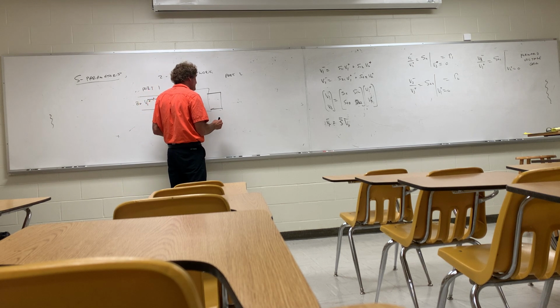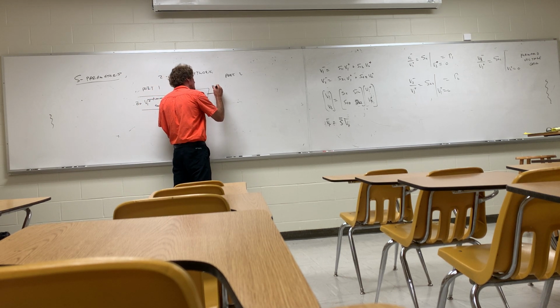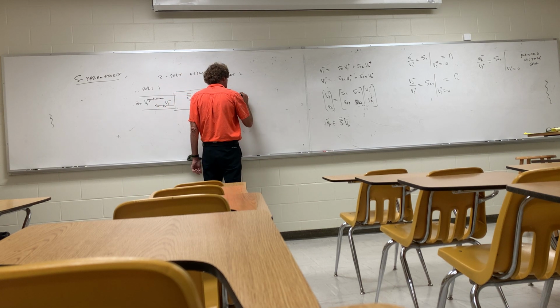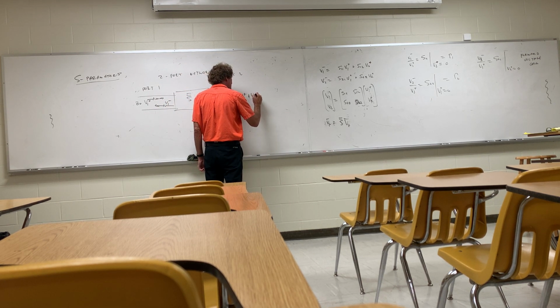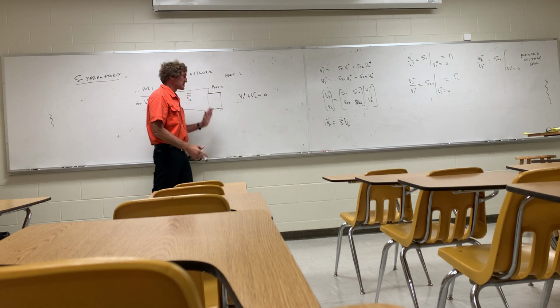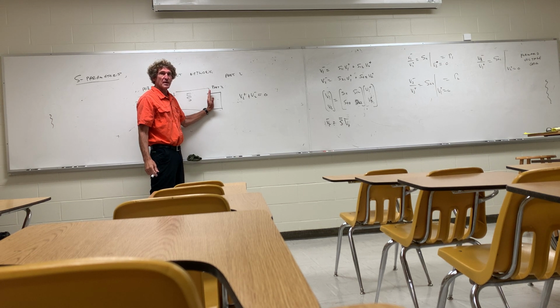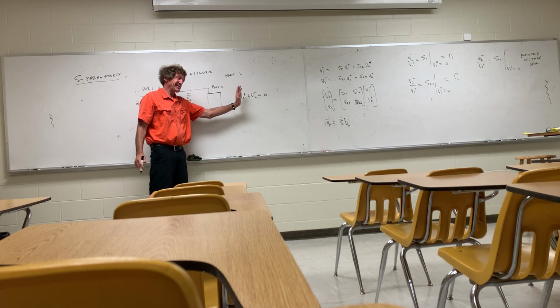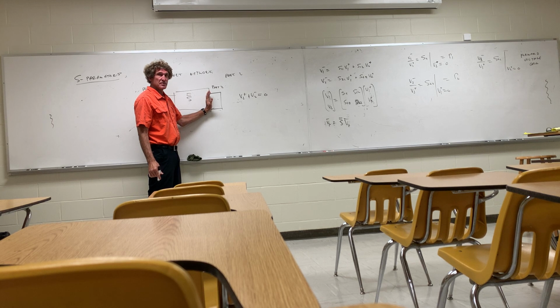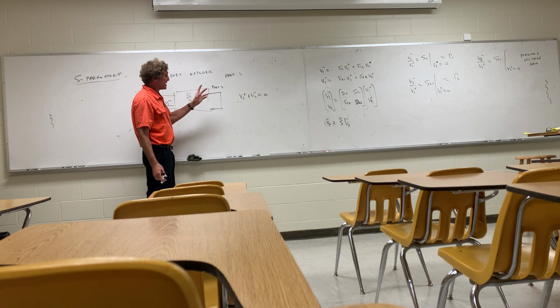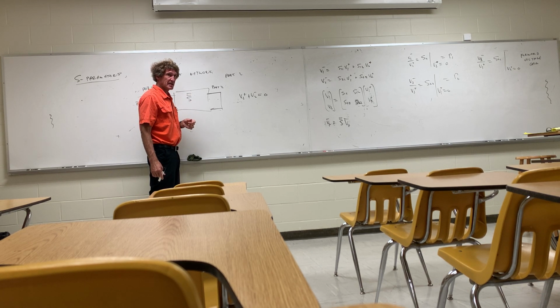This is port 2. By shorting this terminal right here at port 2, what I effectively do is say that V2 plus and V2 minus sum to 0. Y'all follow me? Because when you have a port, anytime you have a transmission line or a waveguide, you have outgoing and incoming waves that superimpose at the point of the port. I'm trying to show you a short right at the port here, not with any length to it, because if it was a little further away, then we would have to change this. But if you look at this, V2 plus V2 minus is 0. It's a short circuit. Do y'all agree with that, class? That's the definition of a short circuit. There is no voltage crossing, which means the plus waveform would cancel the minus if it had any value.